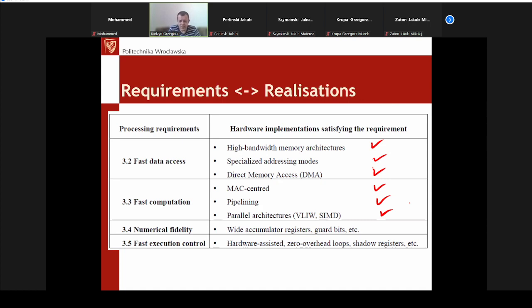Then we've got wider accumulators, registers as well. Such an idea is in DSPs, to increase the precision. So for example, instead of 32-bit microcontrollers, we've got 40-bit accumulators. In 16-bit, we've got 20-bit accumulators, for example. And there are extra features we can expect of special